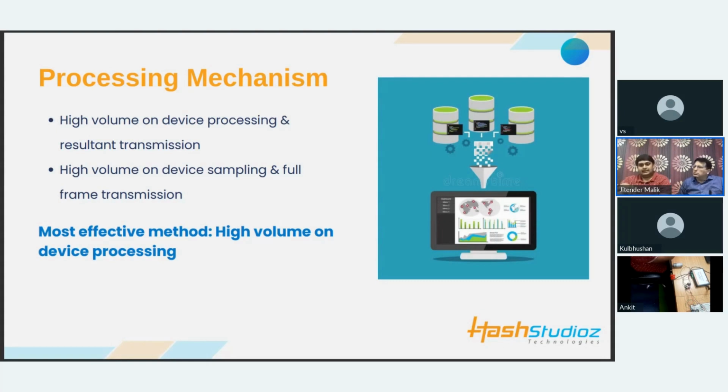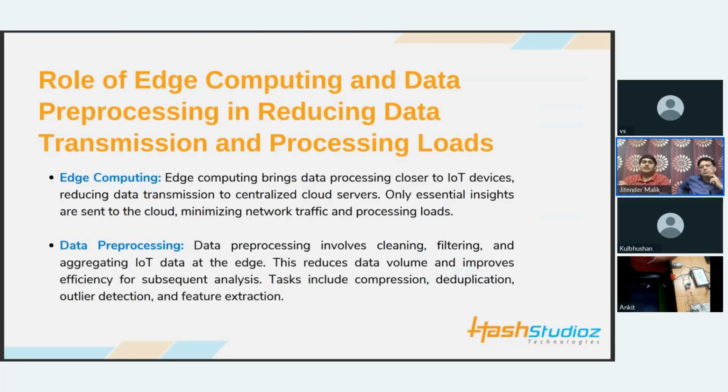Why do we require that high frequency read on the analog section? Because whenever you're doing a vibration analysis, you are trying to predict the anomaly in vibrations on a particular motor or a particular device. We are trying to do aging analysis. You can try to do fault detection, or issues that may arise with the bearings and stuff, or the anomaly in vibration in case of a loaded motor and stuff.